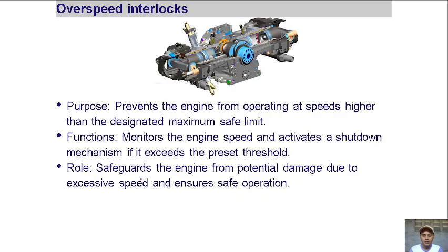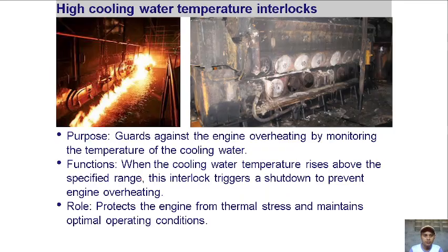Okay, another protection for the engine is the high cooling water temperature interlock. If the high temperature of the engine is not controlled and exceeds its limit, the engine may get damaged, like in this picture. Fire or explosion may occur.